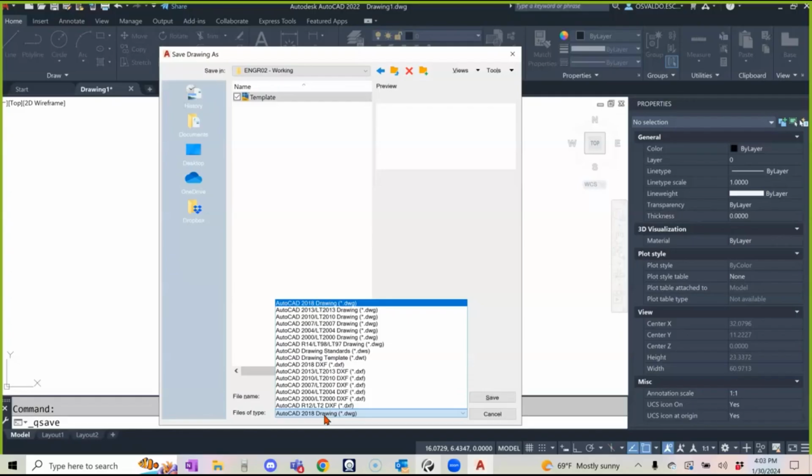You cannot downgrade. If you are working here and you go home and open those files, you can upgrade them. In fact, as soon as you open them, they will change to the 2024 version. But then when you come back to work in the lab, you won't be able to open them because the lab is version 2022. You can only upgrade, you cannot downgrade. Does that make sense? So the version that you need is 2022, not 2023, not 2020, not 2024, 2022. Thumbs up.